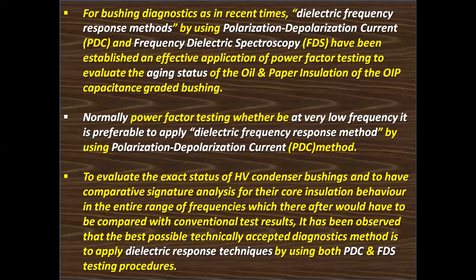To evaluate the exact status of HV condenser bushings and to have comparative signature analysis for their core insulation behavior in the entire range of frequencies, which thereafter would have to be compared with conventional test results, it has been observed that the best possible technically accepted diagnostic method is to apply the dielectric response method by using both PDC and FDS.